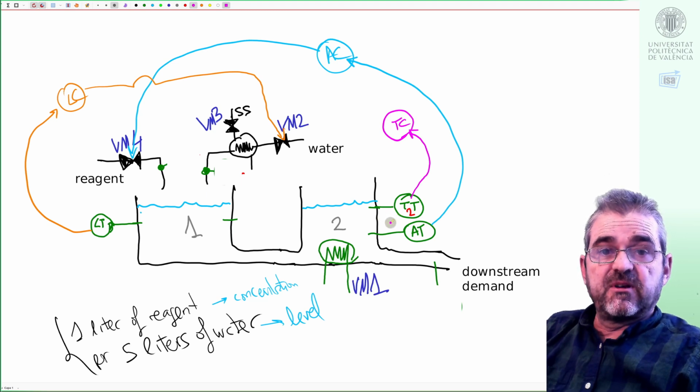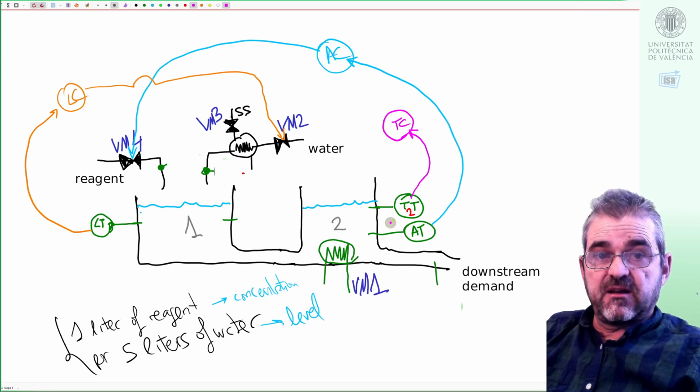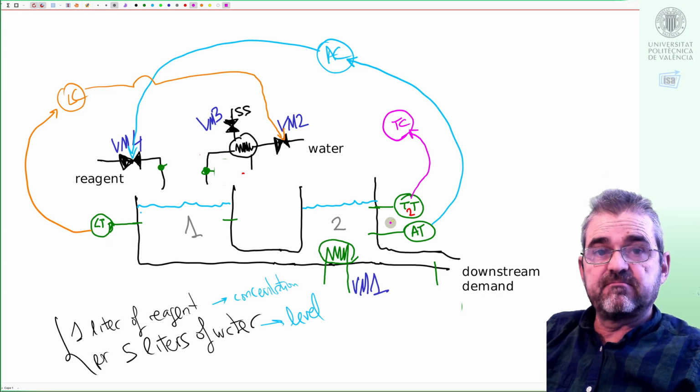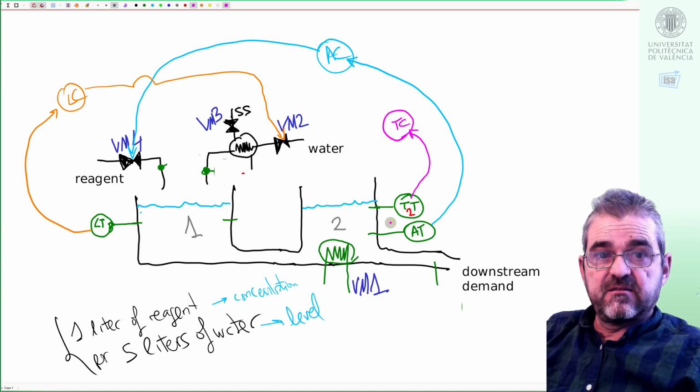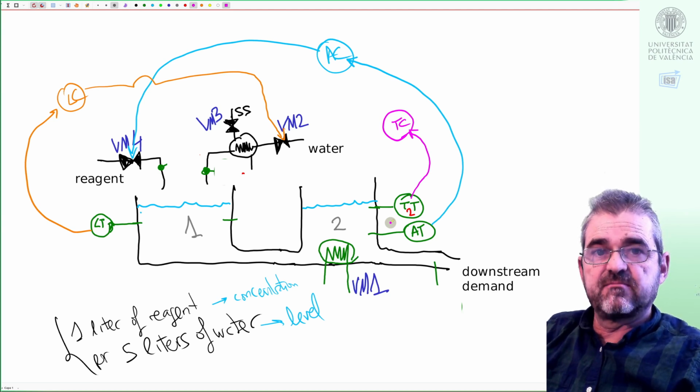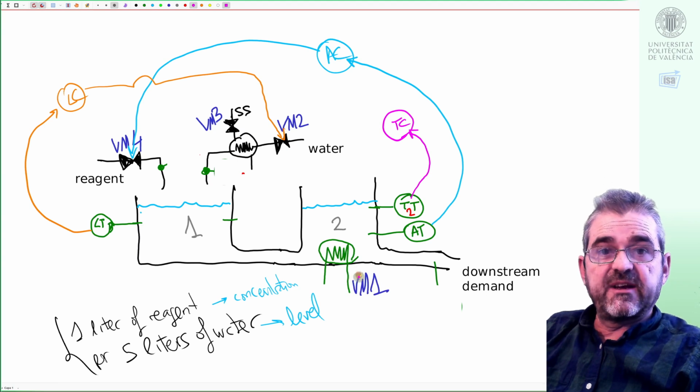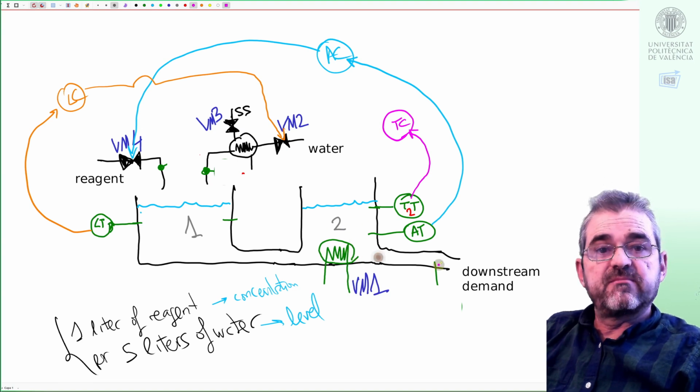Well, there are some advantages and disadvantages on each of them, and of course it also depends on the dimensions. On the one hand, common sense argumentation would tell that I would choose as a manipulated variable an actuator with fast dynamics and large effect on my controlled variable: high gain, high bandwidth, low time constant. However, we can imagine that in this case our VM1 actuator will be fast because it's heating a small tank close to the outlet pipe.